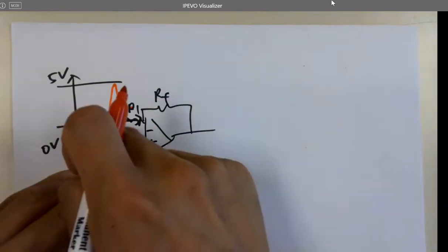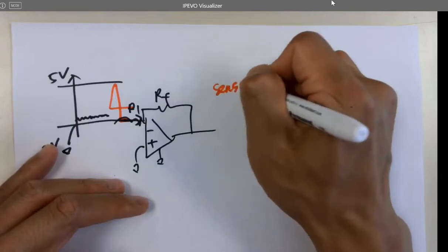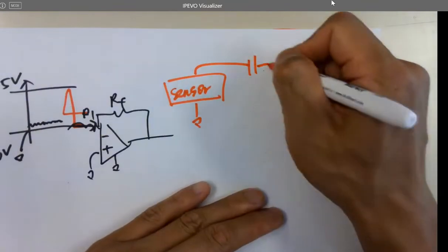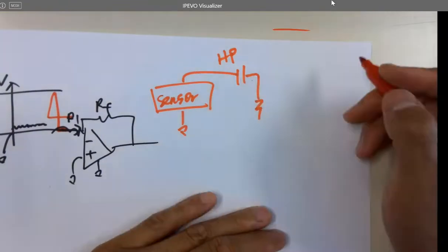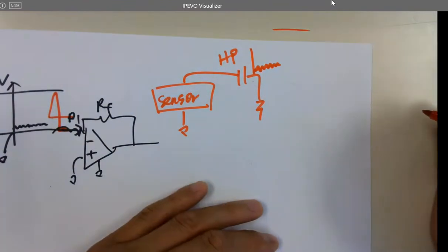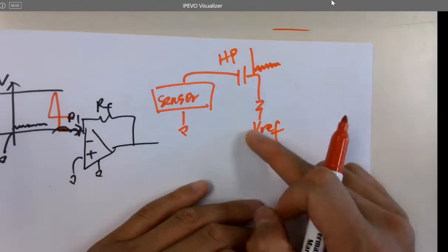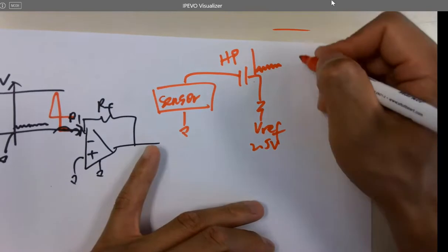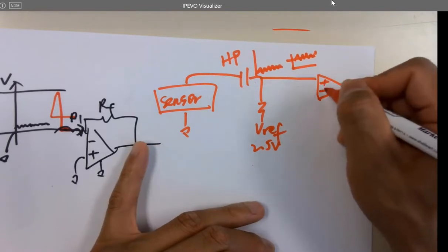So usually if you have a sensor output like that, what's the first thing you want to do? Sensor output signal, so you want to remove the DC offset first. High pass. So after that, everything is down to the ground. And then lifted. Superposition. Provide a DC voltage here. Okay, you can lift it to here. And then do that thing.